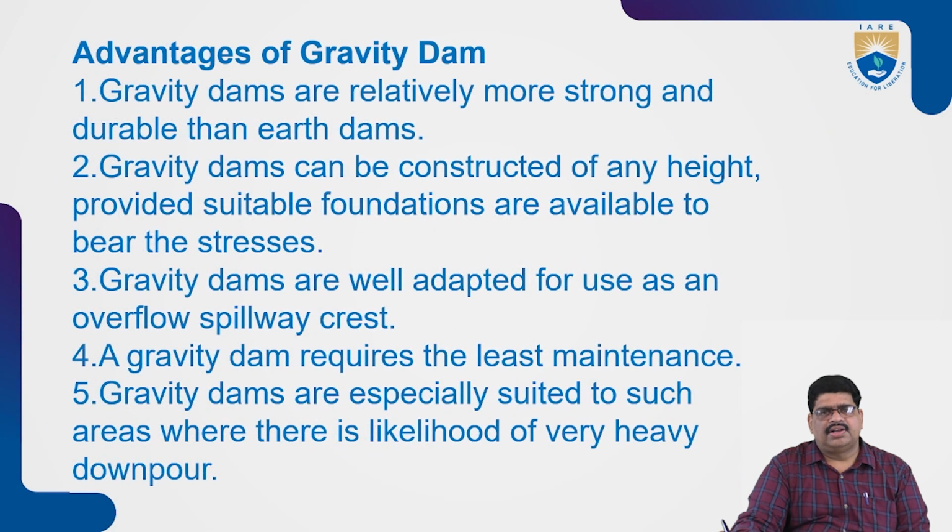Next, what are the advantages of the gravity dam? The dam is relatively strong and durable, as we know. The maintenance cost is very low. Gravity dams can be constructed to any height as required, based on the survey reports and functions, and the availability of the foundation is very important. Next, gravity dams are adapted for use as overflow spillways.